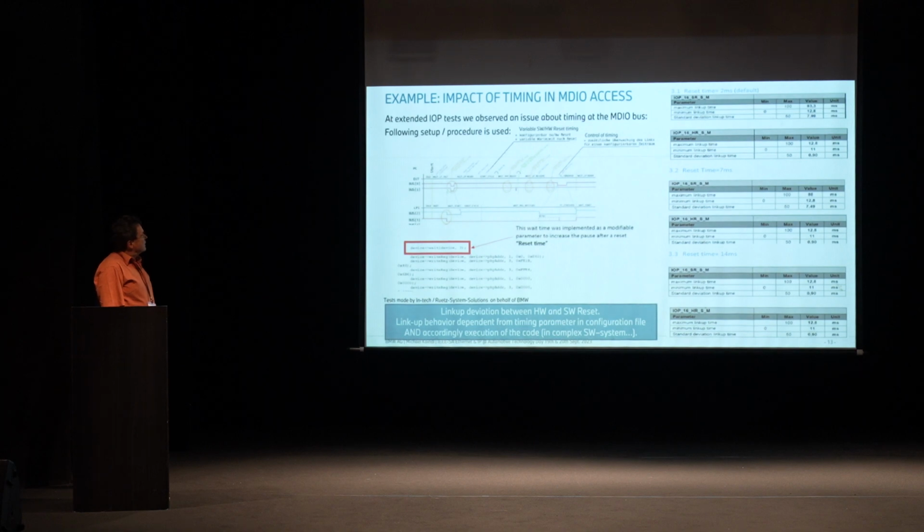Look at timing. During the tests, we use the timing, make a reset, and have introduced a variable as a tester variable: the time between executing the commands. Very simple: write the register, reset, wait the time, write the register, wait for the reaction. And we do it for the link-up time. If you use a default time of 2 milliseconds, the link-up time is very, very long.